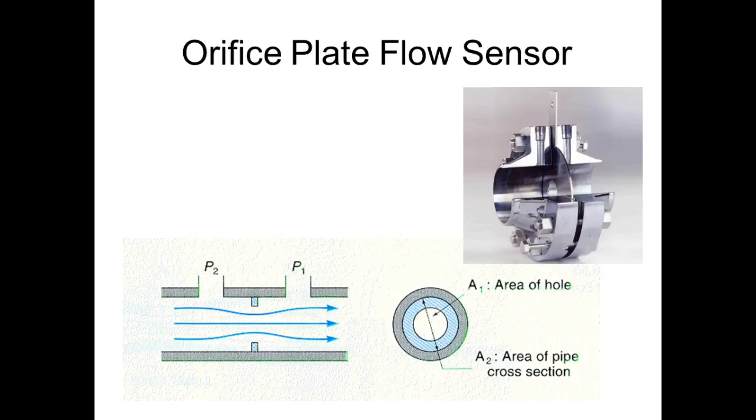So here comes this flow flying through here. It hits this orifice. It's going to build up pressure on this side, and the pressure over here is going to be less. The pressure drop through the orifice is going to be directly proportional to the flow, right? It's just like we say, I is equal to V over R. So it's directly proportional to the opposition, right?